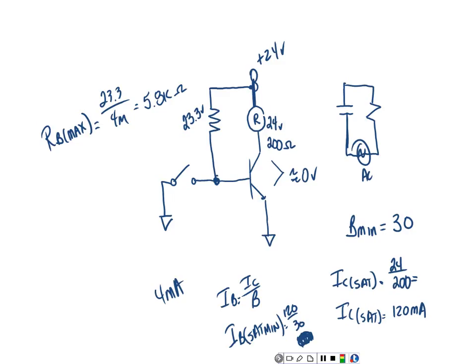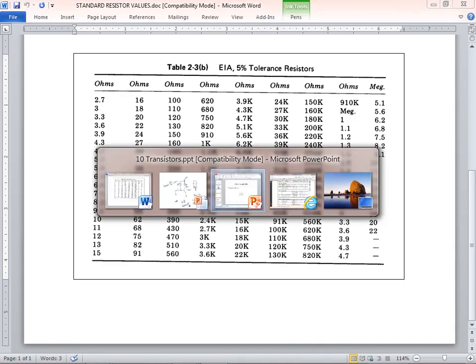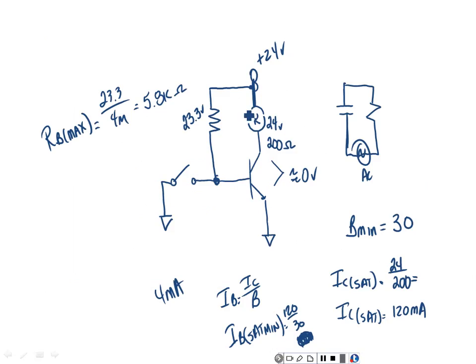The relay is a coil, and when we energize the coil, it's going to drop 24 volts. A magnetic field is going to build up around that nice big coil. It's a DC coil, with hundreds and hundreds of turns of wire, because the only way it can get its resistance is by the gauge of the wire and the length of the wire. So you'll see these DC relays have tons of real thin wire.